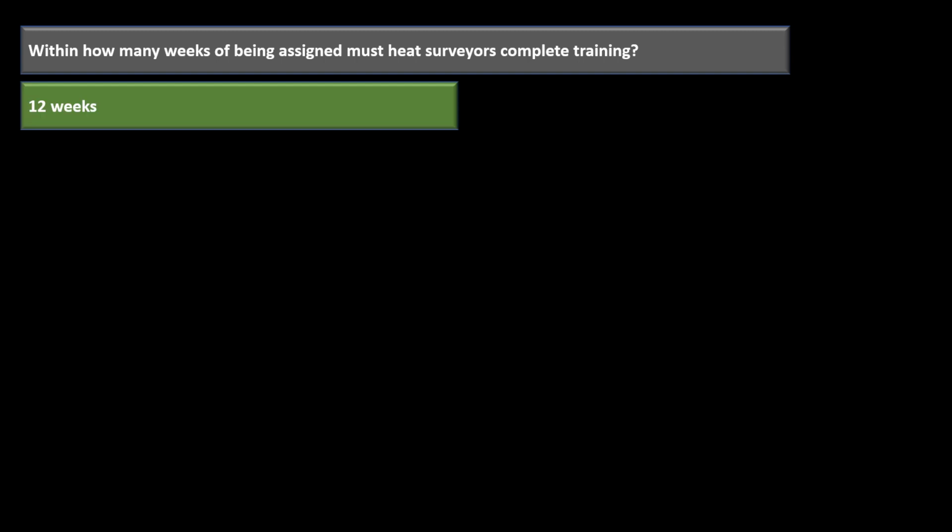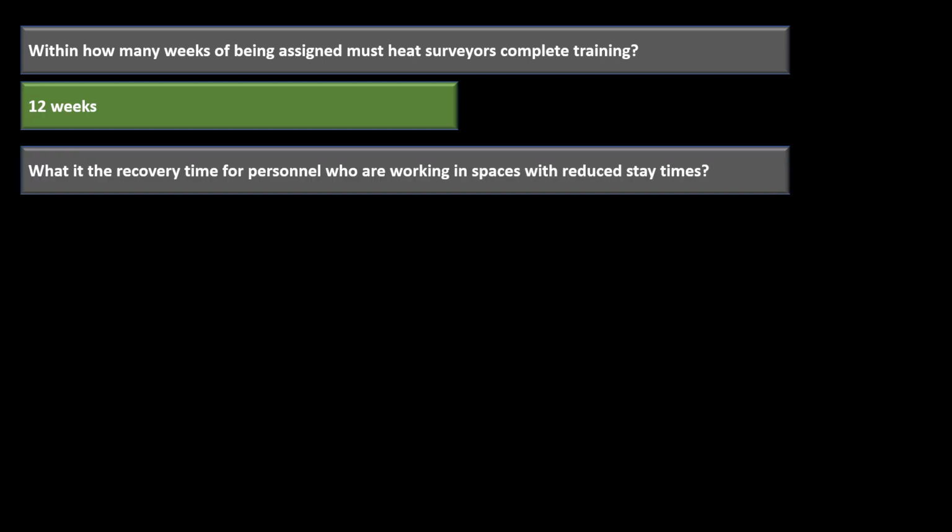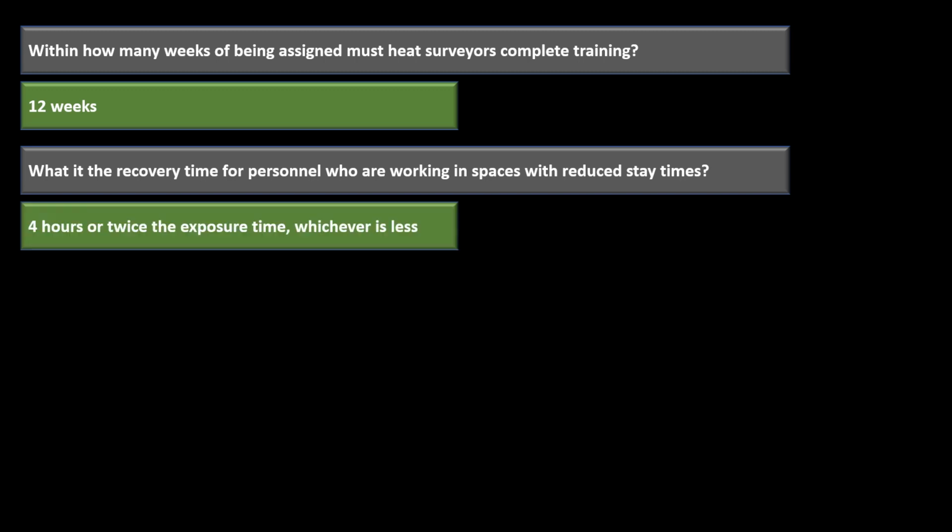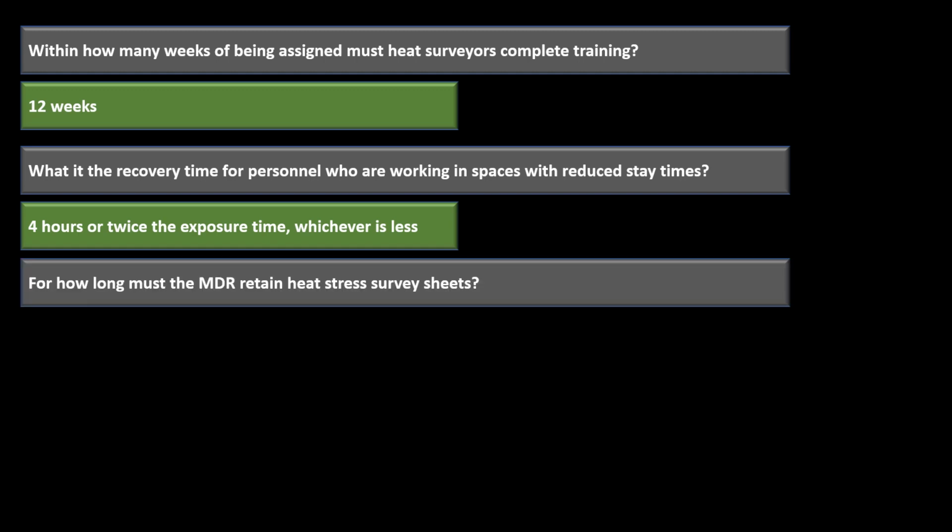Within how many weeks of being assigned must a heat surveyor complete training? They have 12 weeks to get that done. What is the recovery time for personnel who are working in spaces with reduced stay times? It's going to be twice the exposure time or 4 hours, whichever is less.